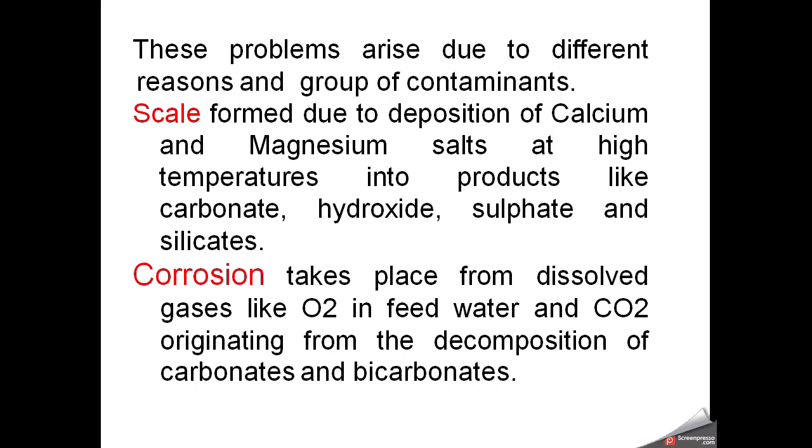Scale is formed due to deposition of calcium and magnesium salts at high temperature into products like carbonates, hydroxides, sulfates. So when calcium and magnesium form these compounds, like calcium carbonate, calcium sulfate or magnesium silicates, they settle at high temperature in the boiler. This is called scaling.